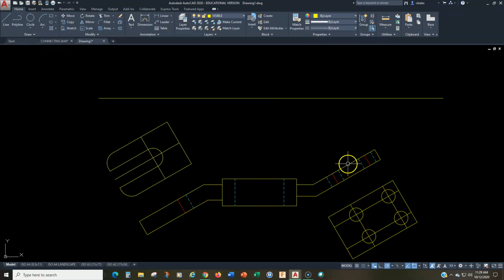On the other hand, this surface and this surface and this surface and this surface in particular are not parallel to the plane of projection. So when we project these surfaces through the projection plane to the top view, they will be foreshortened. Okay, so there's the problem.